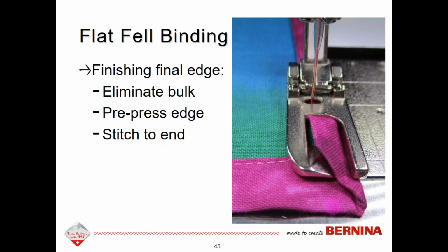Repeat that question, I didn't get it. Sure. When you were cloning the French flowers, you used the toolbar. Can you just right-click and move a copy? You can. A clone is a right-click and a drag. I could copy and I could paste, and then I'd have to move that copy away from the original. Either way makes a copy. It's just another way to make a copy. When you clone something, though, you're right-clicking and dragging, and when you drag, you can place that copy away from the first design or the design you cloned.